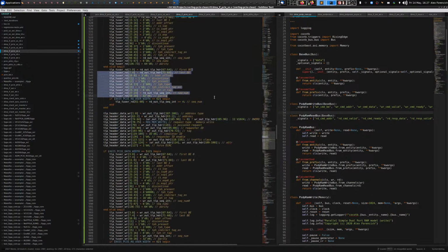One thing that I'm scratching my head over right now is resource consumption. It's similar, but I think it's about 1,000 registers, 1,000 flip-flops higher. And I haven't figured out exactly where that's coming from. That's basically 2 register slices across the 512-bit interface.